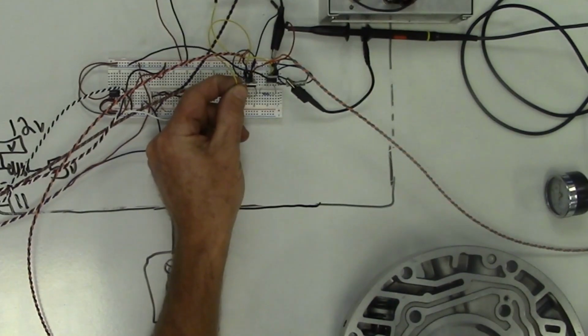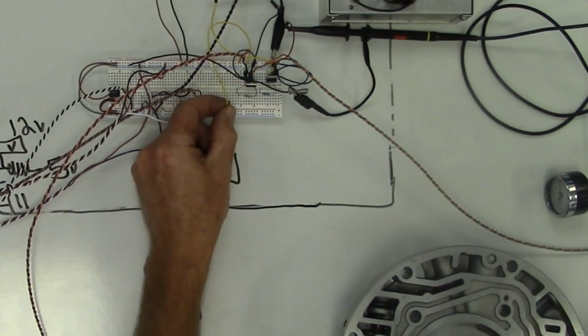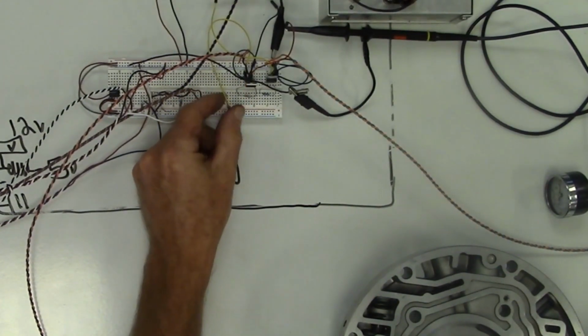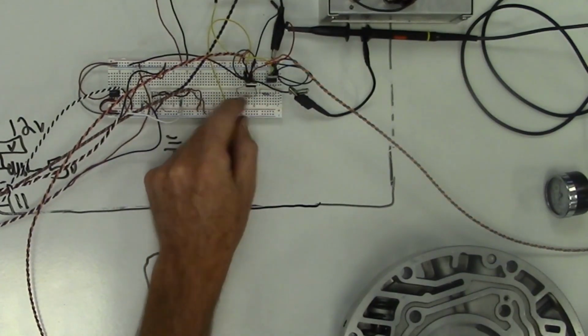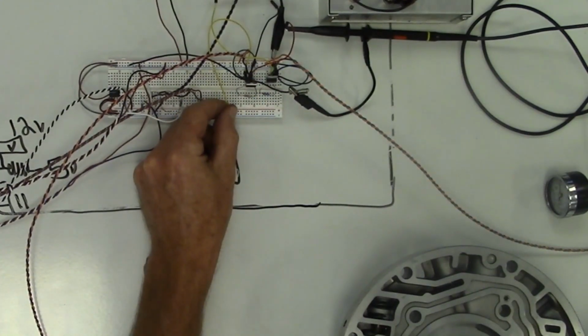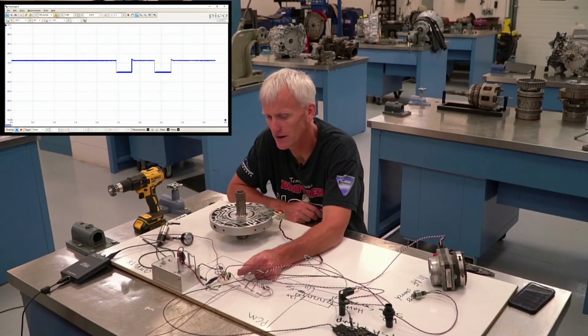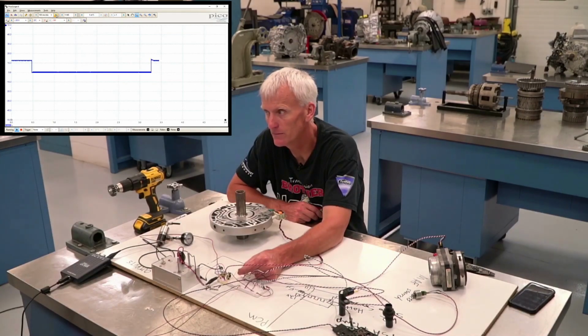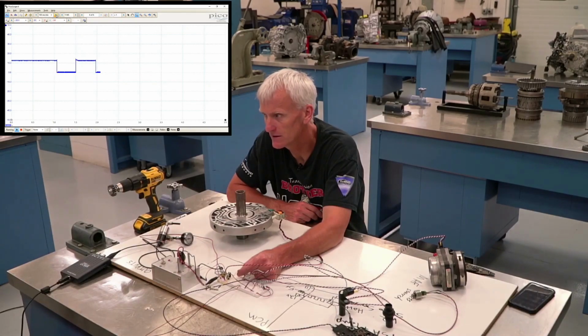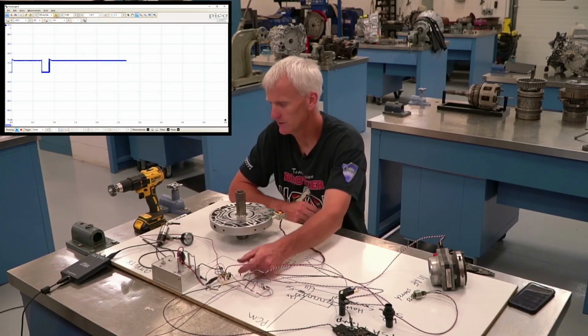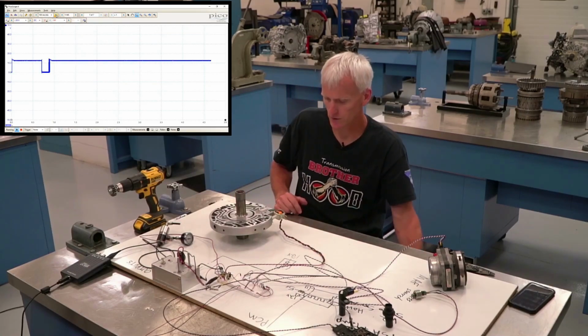So when I energize it, hook it up to 5 volts or so, it's going to allow this solenoid to turn on. So you can see when I ground this circuit out, voltage drops to 0. When I open it up, it bounces back up to 12. Normally you'll see an inductive kick with the solenoid. I don't know why we're not seeing it on this. It's probably the way I have it wired up. But either way, it'll still work for how we need it to work.